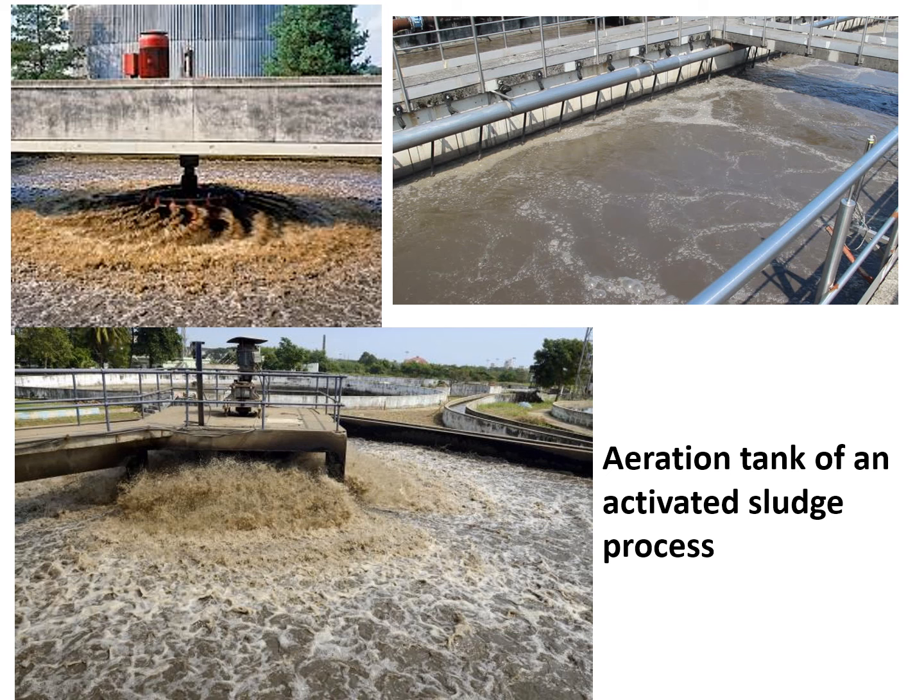Next is your activated sludge process, or aeration tank. It's a biological treatment process. Here an active mass of microorganisms is kept, and here you can see the aerators. These aerators are constantly supplying air and oxygen to the microorganisms, and these microorganisms use organic matter as their food and degrade it. They are responsible for the degradation of organic matter. So it's a purely biological process.